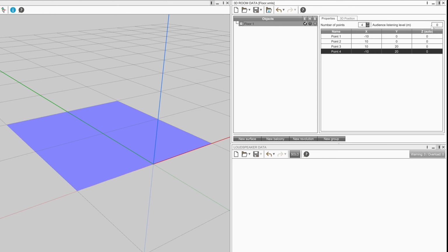When a venue is modeled in Soundvision, the physical surfaces are drawn. We can draw the floor at a height of 0 meters, but when an audience member is on this floor, their ears are not at a height of 0 meters. If the audience is standing, this could be a height of 1.7 meters, or if they are seated, a height of 1.4 meters.